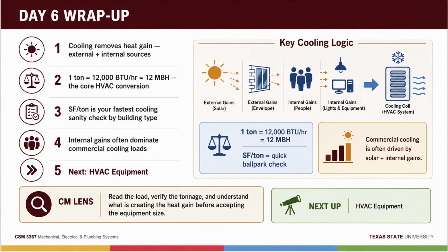Heat that changes air temperature? Sensible. Heat carried in moisture? Latent. Total cooling load equals? Sensible plus latent. The conduction equation? Q equals U times A times delta T. And U in terms of R? 1 over R. So an R-20 wall has a U of 0.05. What does CLTD stand for, and why does it exist? Cooling load temperature difference. It replaces plain delta T to account for solar heating of the surface and thermal lag.